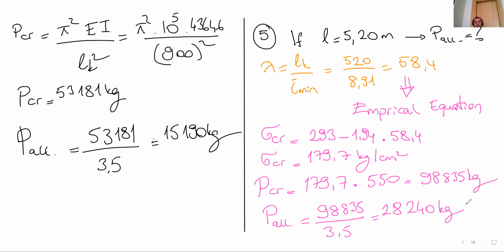We can check the loads given on the structural system, if it works or not. To decide it, we need to find the allowable force and compare it. If we have a force greater than the allowable force, the system will fail. It doesn't carry that load. The given load should be less than the allowable load to carry it safely.